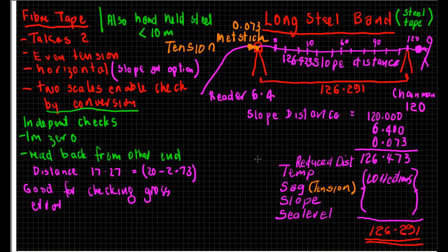So what happens is you're at your theodolite end, and you've got a chaining tripod over the other mark, and your chainman will walk out from the theodolite to the point at the other end and stand there.